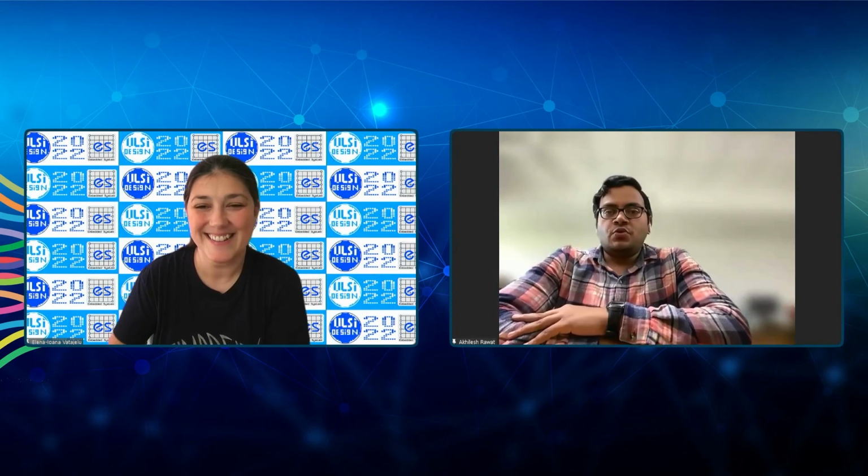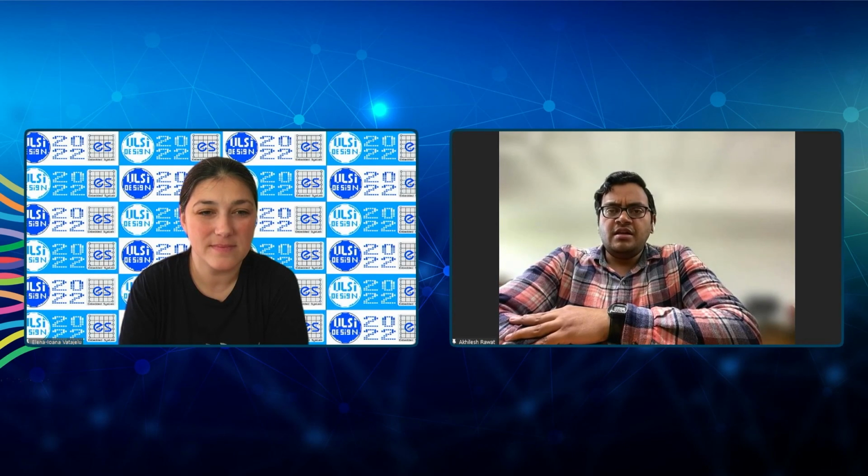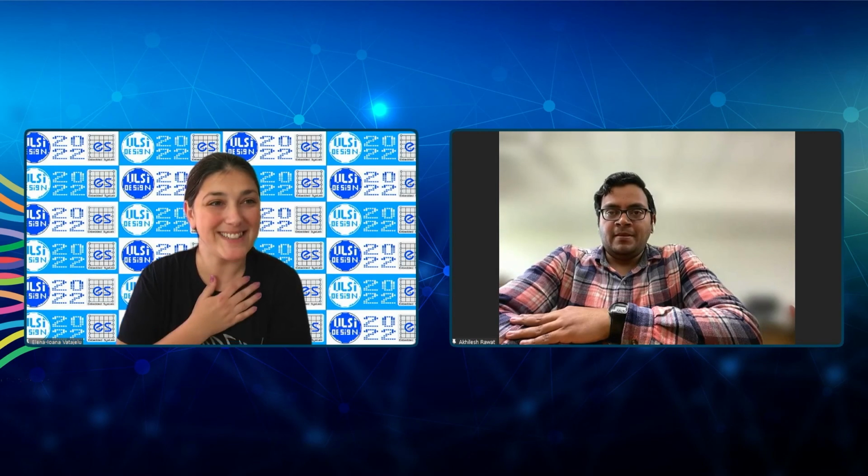Okay, sorry. So yes, it is the channel thickness actually that helps us greatly in achieving a shorter channel length, because the scale length in this case would be lesser. Also, since it has a stacked structure, the dangling bonds would be less compared to conventional material, say silicon or other materials. And what would you say? Yeah, sorry, go ahead. You didn't finish.